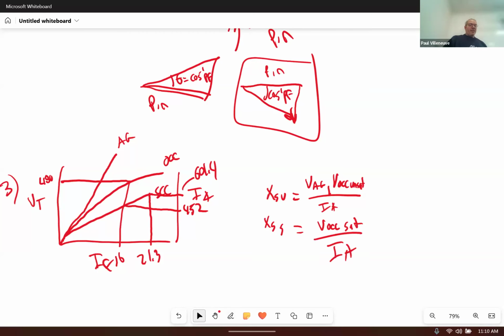So now looking at this data, the only thing that I haven't identified is this point right here. This is 14.7 on the air gap line when it reaches 480 volts. Okay. Or if we want to be a little bit better, because it's a Y-connected machine, why don't we just go ahead and put that as a single phase equivalent? So we'll do 480 divided by the square root of 3. And with this information, can you calculate X sub S unsaturated and X sub S saturated?